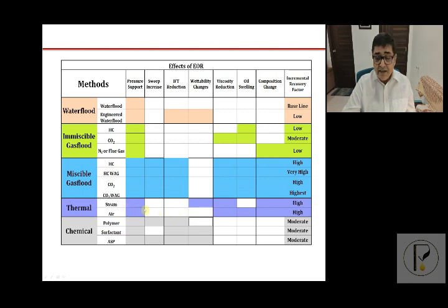Air injection has now moved from heavy oil to light oil, and many operators are testing it in medium gravity too, where polymers are not effective because the temperatures are either very high, or maybe too deep, or reservoir pressure has declined.